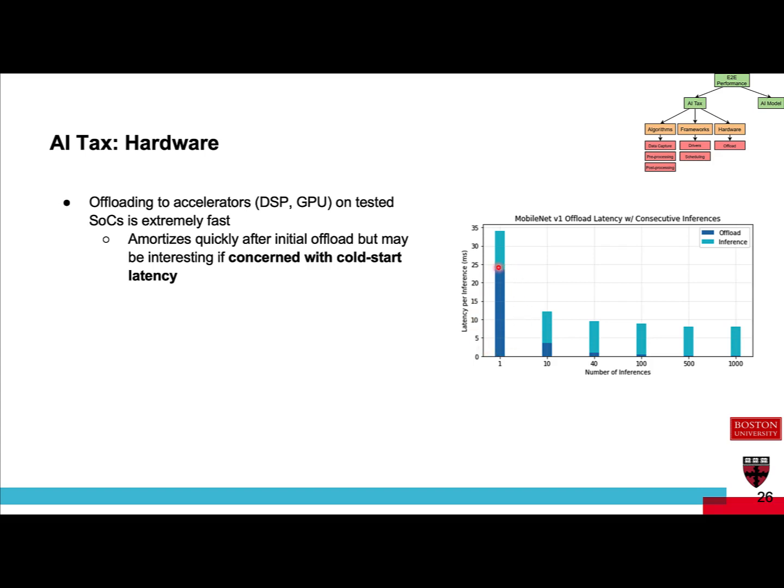During the initial offload, the overhead ends up being big because the operating system has to do a lot of setup and get the accelerator actually ready. So this means that the accelerator needs to be primed before executing it. Now, in the context of benchmarks, these kinds of behaviors are actually not measured. However, in real-world applications, you are not going to keep the IP primed up at all times because that's inefficient from a power consumption perspective. So these kinds of cold starts can actually be quite critical for user experience.